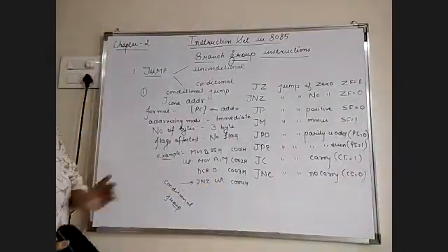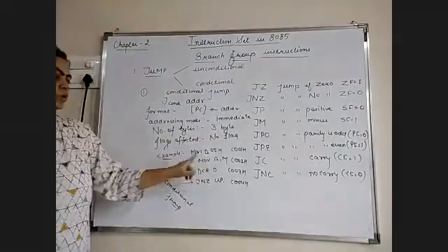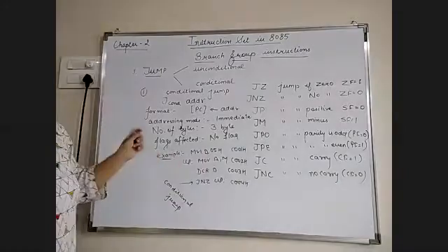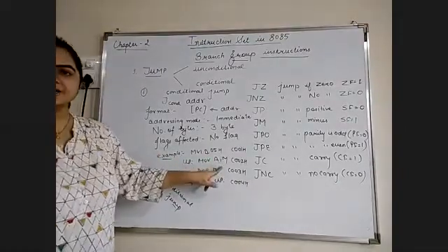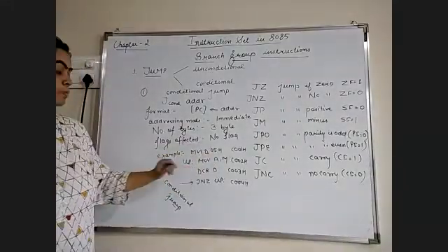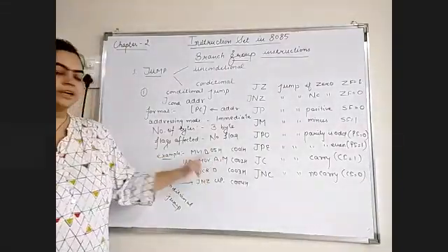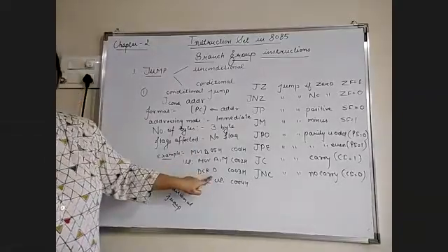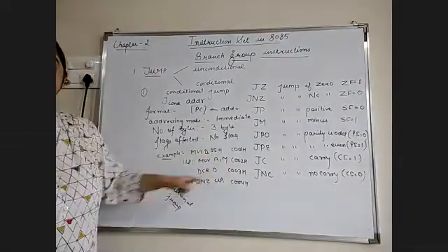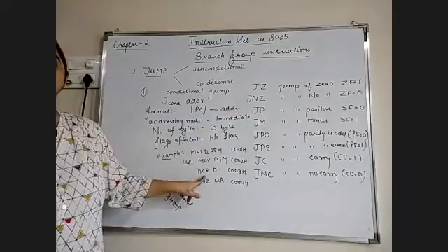So this instruction means initially we assign 05 to the D register. So by this instruction D has the value 05. Next we assign whatever is in the memory location pointed to by the HL pair into the A register. We did these instructions in the data transfer group. After transferring the data of the memory location into the accumulator, now we decrement the contents of D. Initially D has value 05. After the execution of this instruction, D has value 04, because DCR decrements the register value by 1.